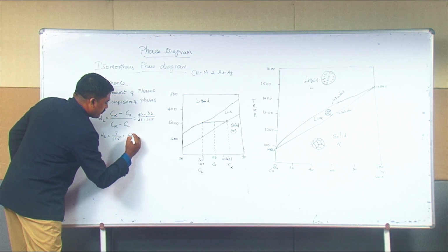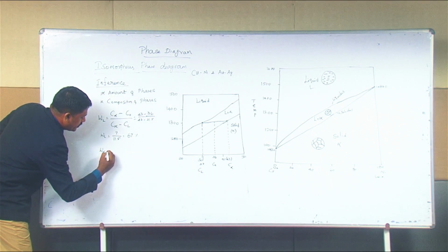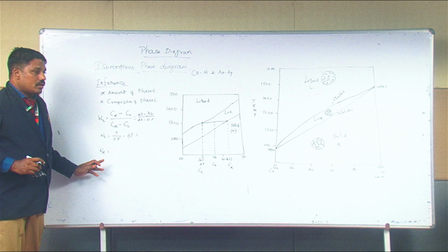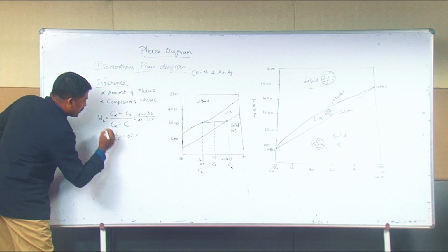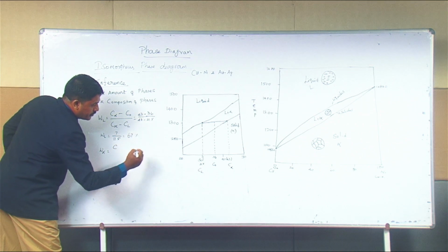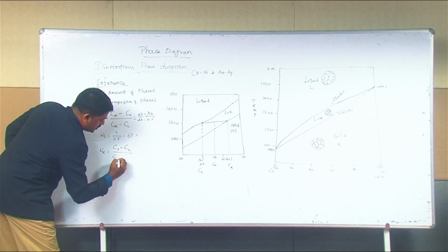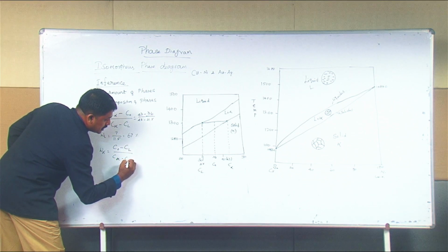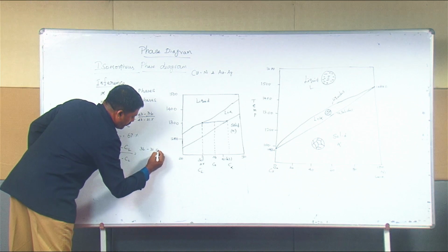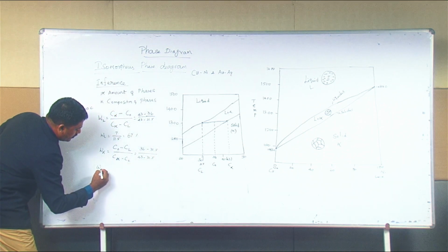6 is 67 percentage, and W alpha. So W alpha is the amount of solid phases in the region for a specific temperature, that's 1300 degrees Celsius. So W alpha is equal to C0 minus CL divided by C alpha minus CL, which is equal to 36 minus 31.5 divided by 43 minus 31.5. So that is equal to W alpha.